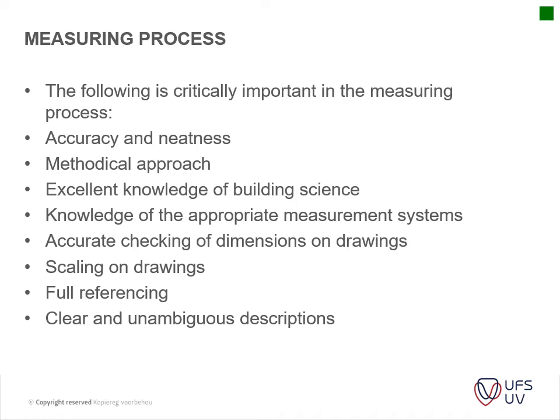Then the measuring process itself, the following is critically important: accuracy and neatness. Obviously, if there's any change to a design, you should be able to go back to your measurement and only amend that section that was changed. But if you did not keep track of your measurements very well, it will necessitate a total remeasurement of those items, because you do not know where it stopped and ended. So please be aware of that. It should be very methodical.